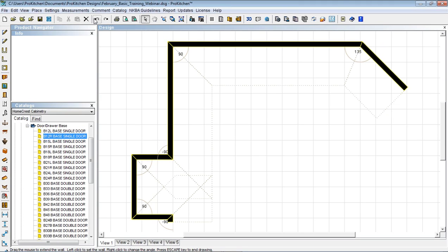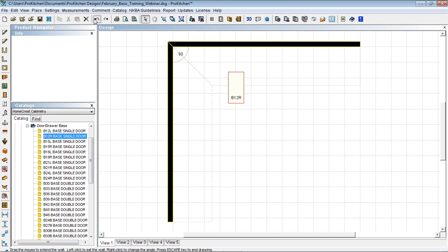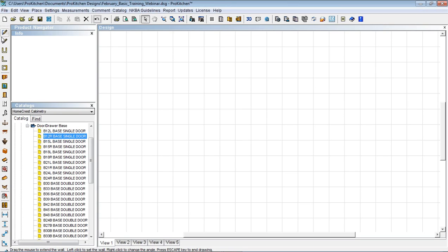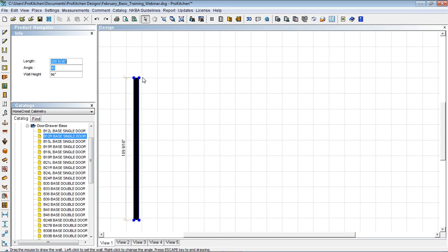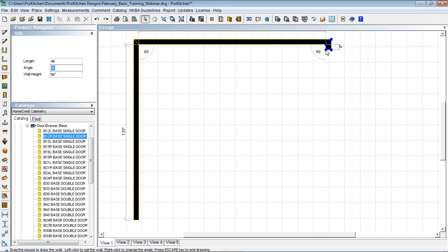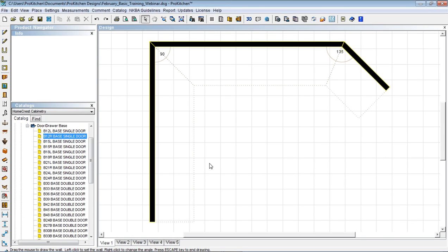Now, I've found most designers will use the freehand pencil, where I can just left click, push up, do 135, enter, 144, enter, 48, tab, 135, enter, 0, enter, and it's done. And then I do my extrude here if I wanted to do that.